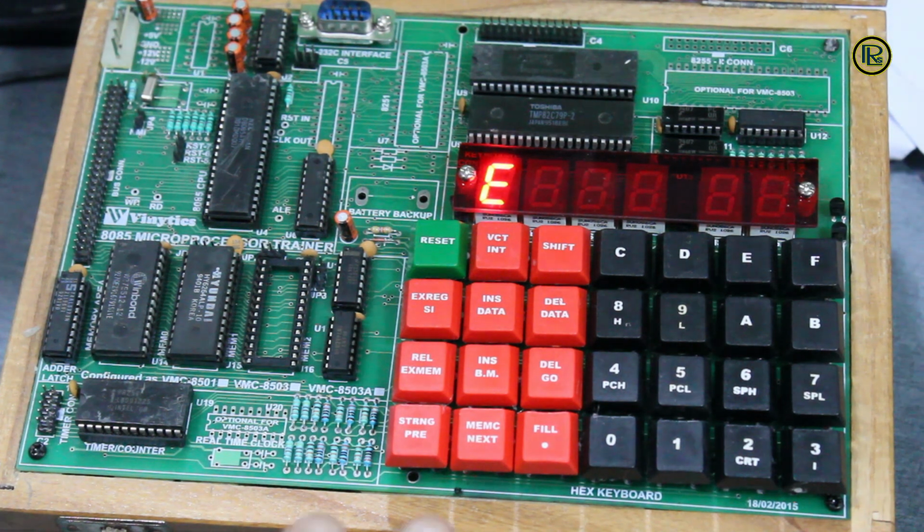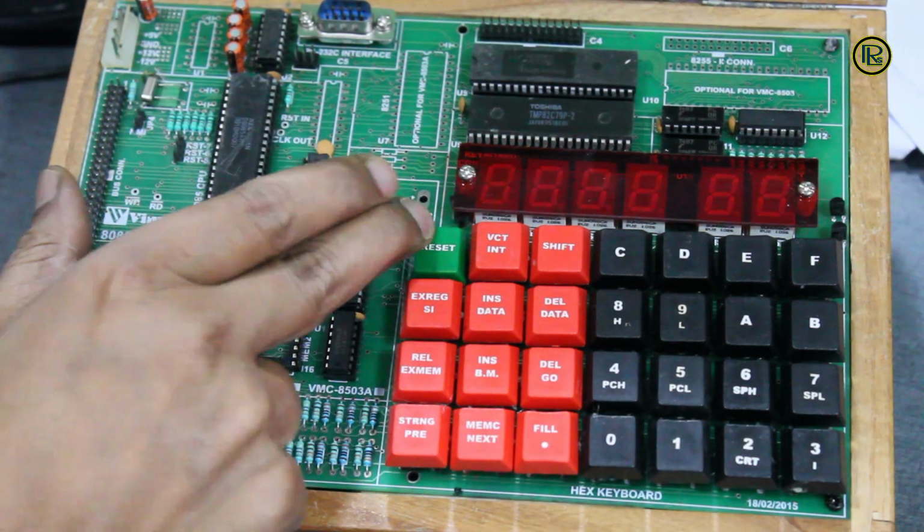So after executing the program, what has it done? It has added the two numbers, that were 3A and 8F. And what will be the result? The result will be C9. And where will the result be stored? The result will be stored at the 2052 memory address. So now I have to go to the memory address to check whether I am getting the result properly. So now again I have to reset.